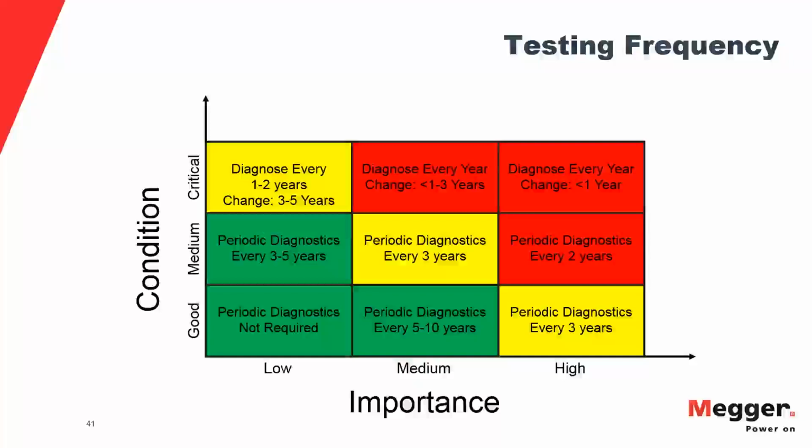So for instance, 150, a few hundred kilohertz, and then up into the megahertz is this partial discharge frequency band. And when you do it online or with handheld in the substation for switchgear and so forth, you typically have the choice between several different sensors feeding into the system. So you have UHF, and then you also have radio frequency antennas for certain applications. When you do your frequency sweep there to find sources, you're doing this in the different bands.